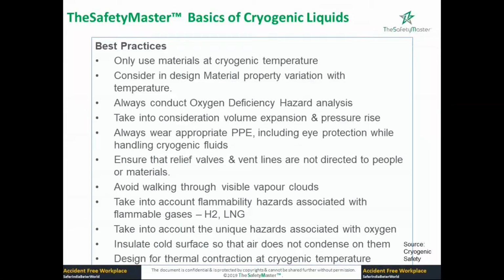It means he has undergone the training, or he has the PPE required for entering there, or he's aware of the hazards, and there is another person monitoring it. He has an individual oxygen monitor in his pocket, and there is an oxygen detector inside the room.